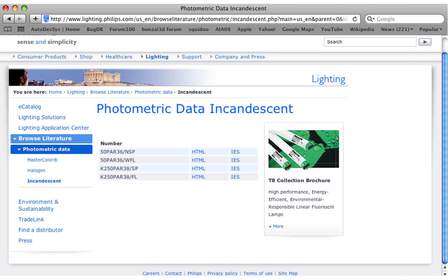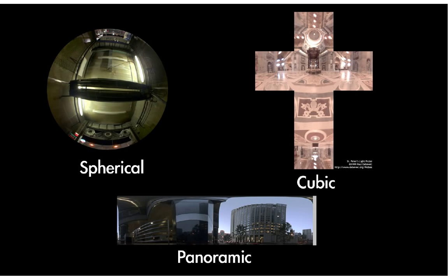You can also create a custom light, so you can download any standard lighting data file. We support all of the industry standard data formats, so you can go to the lighting manufacturer. They have all of their products and fixtures, and the lab data for them is recorded. All you have to do is load that lighting data file, and then that light source will radiate light based on that lab data. So that would be an extremely accurate way of doing it.